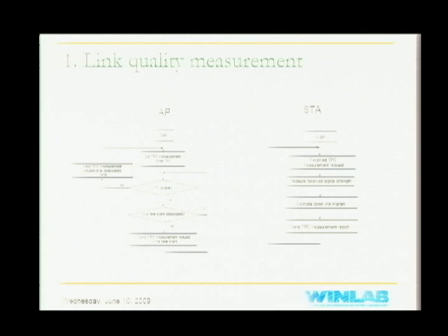Link margin calculation here is straightforward because the target data rate in our case is the maximum data rate, so we know the sensitivity value corresponding to it. The received power and sensitivity are subtracted to get the link margin. It embeds that in the TPC report element, also mentions what transmit power it is currently using, and sends it back to the AP. That's all the station does.